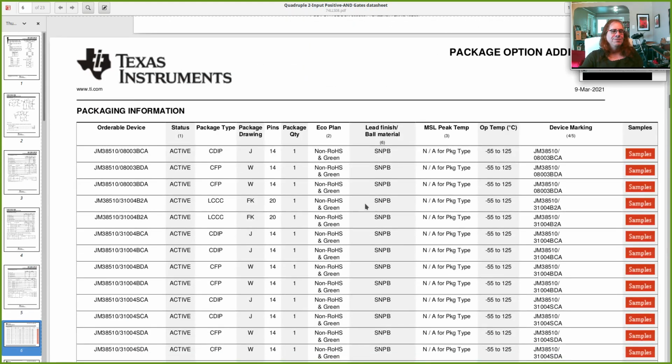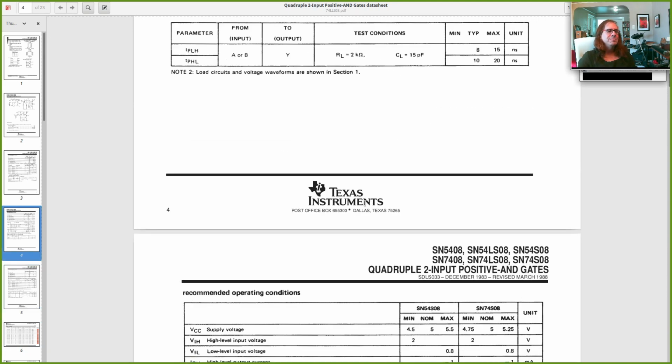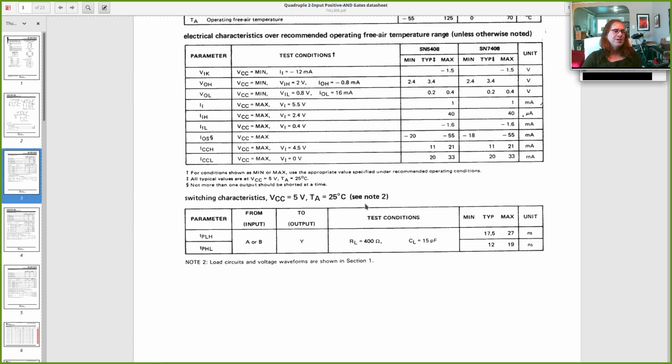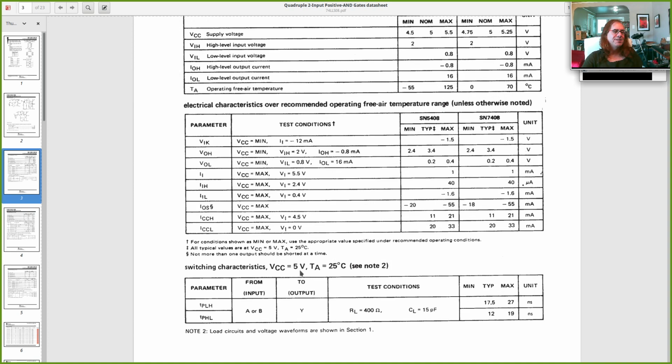Well, and also the temperature that you're currently operating at is going to change the... Right, right. So these numbers are given for exactly 5 volts, 25 Celsius, which is considered room temperature. But if you're running this in a higher temperature, it would probably switch faster. Lower temperature, I think it'll switch slower.